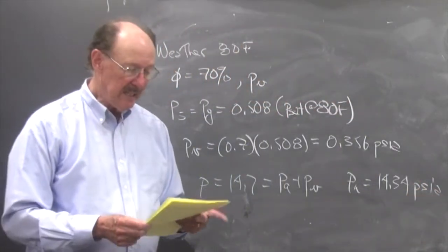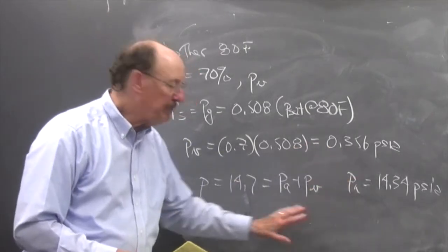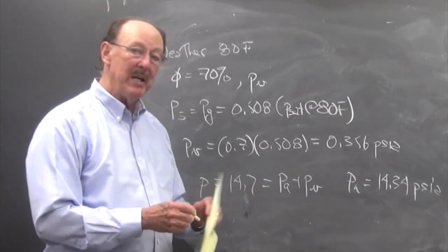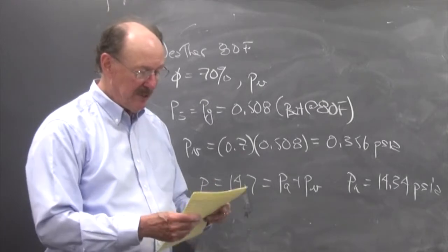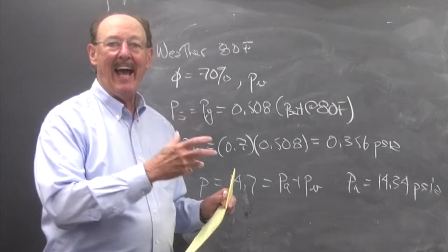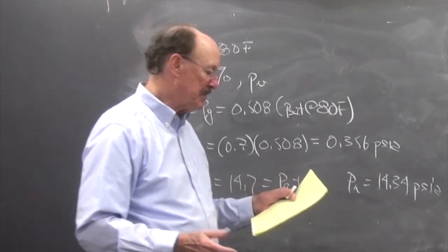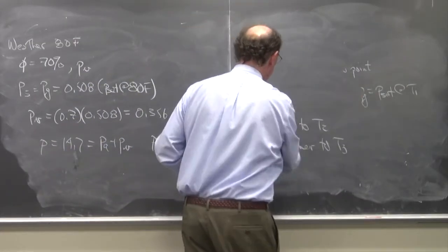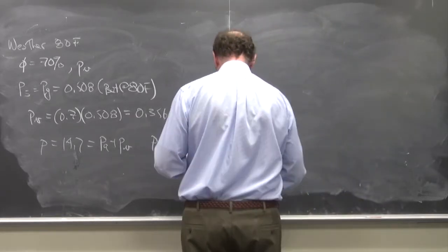So when I'm using the ideal gas mixtures, I want to be able to pay attention to this. Now, one of the challenges that we have with relative humidity is that it's relative, and so in engineering work that isn't as handy as having something that is the actual mass. So we have something called the humidity ratio or specific humidity. It has two terms associated with it, and this provides us with direct information that we can use.